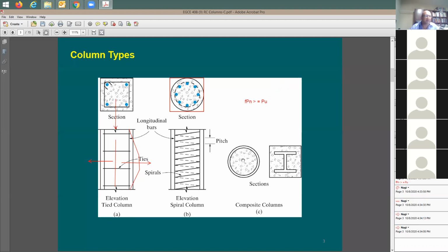How do you think about the strength of it compared to this, compared to no reinforcing at all? You're going to see the strength is extremely high because the concrete doesn't have a place to go. If you want to fail this section here, you need to fail this steel shell first. It's going to take lots of vertical force because the horizontal force here is a fraction of the vertical force.